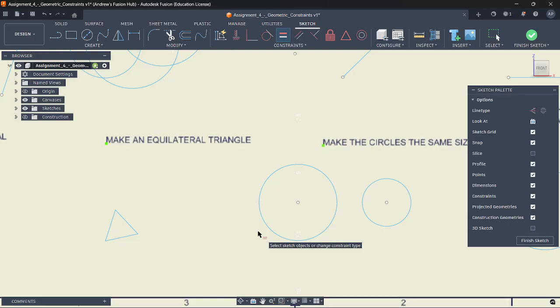Another thing you might want to show them is how to delete one specific constraint. Okay, yes, that's a good point. So this will happen regardless of how good you are at CAD, you'll at some point accidentally make a constraint that you didn't want to make, and then you want to undo it. And sometimes you've done other things afterwards and you don't want to Control Z everything. For me, sometimes if it's too annoying to find, I literally just delete the line or the arc and then I just draw it again and reapply the constraints.